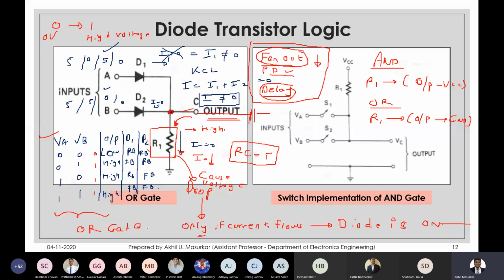So that is why you will get lesser fan out ICs at cheaper cost and higher fan out ICs at higher cost, because the technology that is used to make this resistance is changing. That's where they decide the cost of the IC. Have I been able to bring some clarity, Shubham?